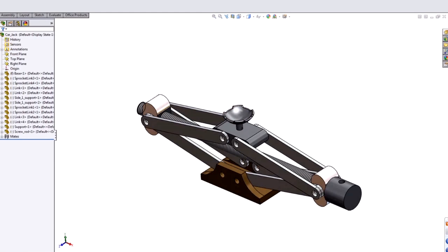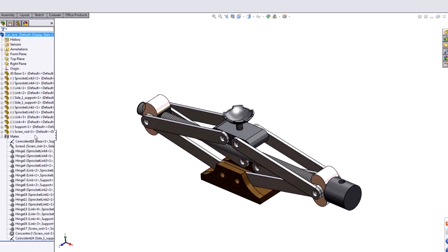Now, the prerequisite for any motion analysis is that when you're right inside of SOLIDWORKS, just in the SOLIDWORKS model, the model should move in the way that makes sense to you. So you want to set up regular SOLIDWORKS mates that constrain the movement such that it moves the way you'd expect. So there's a number of hinge or concentric type mates, just connecting these mechanism elements, these bars together at their position points. And one of the main drivers of this one is a screw mate.